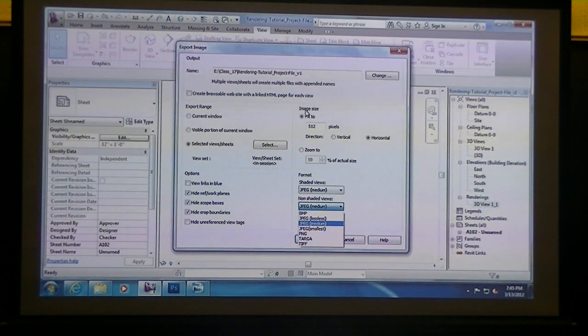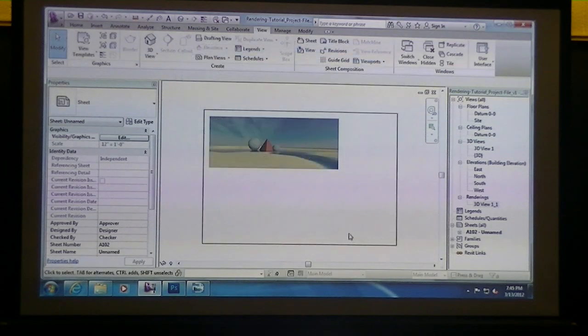Is there any reason the render one would be a lot smaller when you place it on the sheet? It could be possible that when you rendered, your quality was set to screen resolution instead of printer. You just might want to double check that. It probably rendered it at the screen resolution of whatever these screens are.